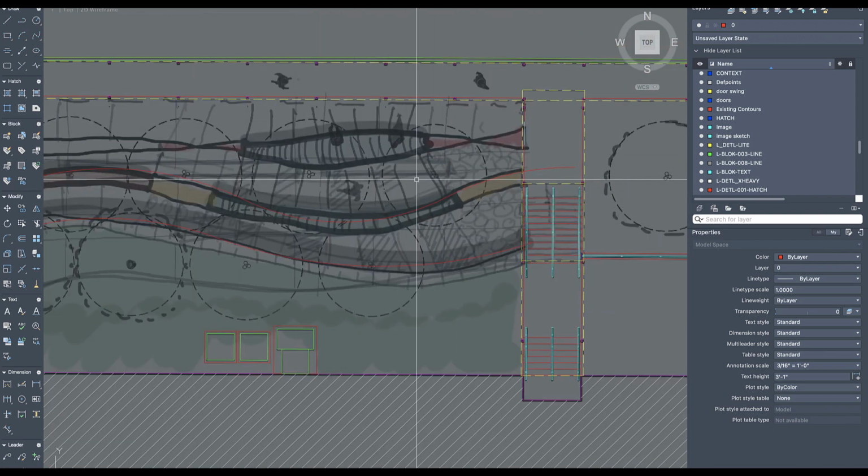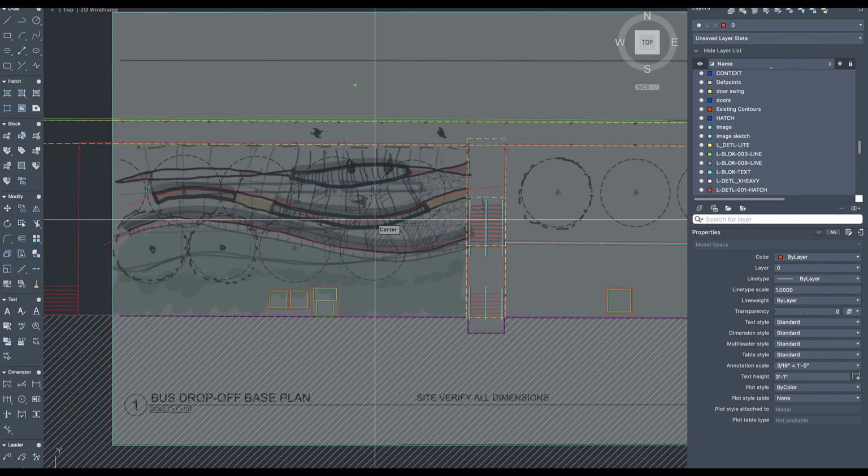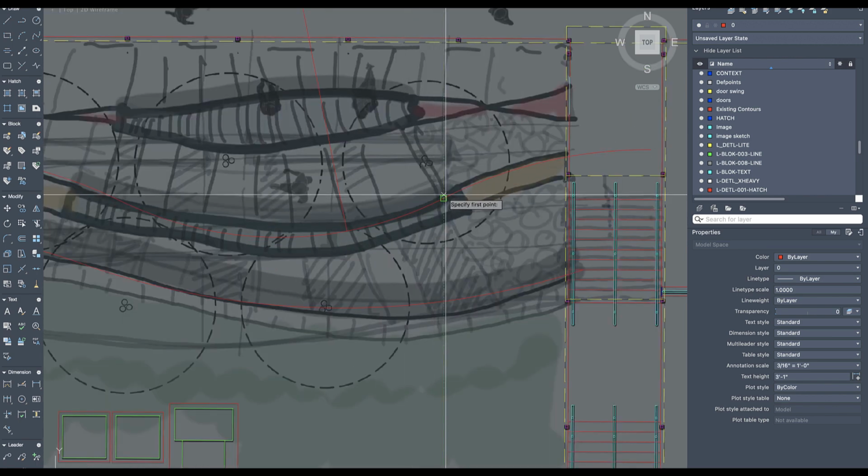These are going to be the guidelines that we're using to sort of run these arcs, these offsets for the benches, especially for this bench right here, and some of the ground plane line work. As you're starting to put in lines, you can start one right here, and instead of just kind of guesstimating, I can even say, yeah, let's snap to the CEN, spacebar. I'm going to go back to this arc right here, and what you're going to notice is that the snap is actually at the top of the screen right here. And so I'm going to click on that arc, and it's going to snap it that direction. I can do this for a whole series of lines right here.